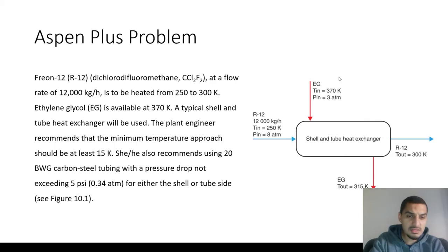Based on these values, I can kind of predict how much flow rate I would use, and this is according to the Cp or the values of the heat capacities. I know Q equals this flow rate multiplied by Cp of the Freon multiplied by this delta temperature, which is around 50 degrees Celsius.